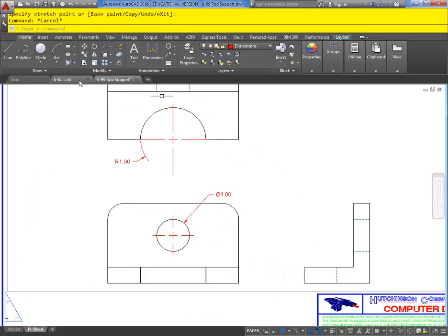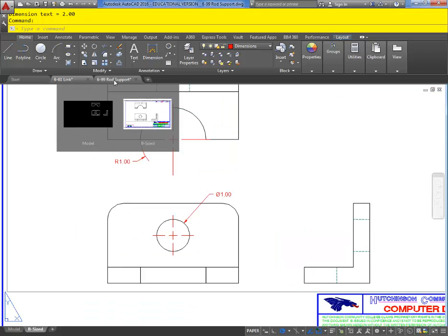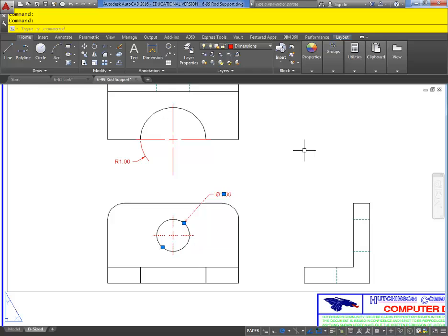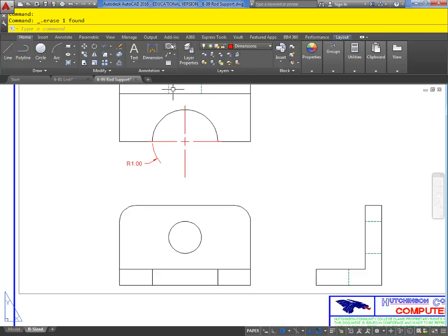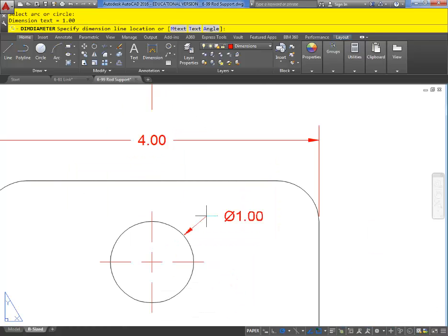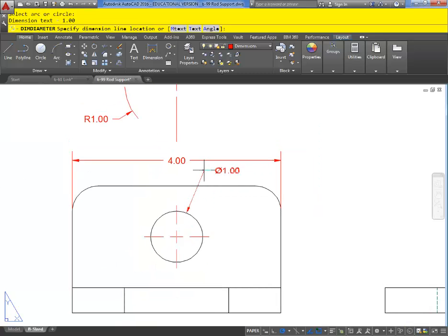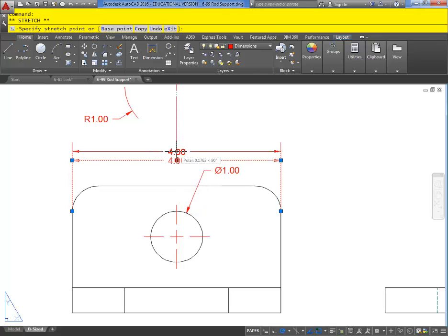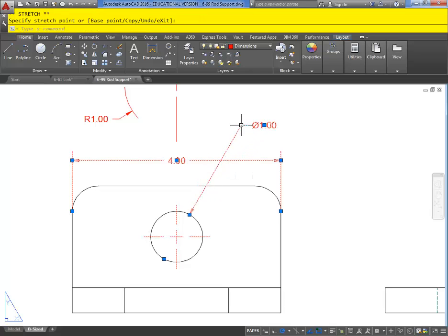One other thing I'll say about dimensioning too is, in my experience, the first rule that gets broken is the 1/2 inch, 3/8. Well, 3/8 not so much, but that first one being a 1/2 inch away. And let me show you why. So if I do a dimension from here to here, and I track off of here 0.5 up, okay, there it is, good. And then if I try to place a diameter dimension, and I try to follow the rule of not putting it on the part, so I try to put it on the outside, but there's not a whole lot of room for it. This one's not terrible, but a lot of times you'll see that we'll go ahead and stretch out these other dimensions, because what I really don't want to do is cross the dimension line more than anything. That's the biggest no-no in dimensioning, is crossing a dimension line.